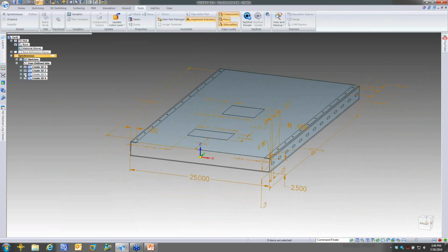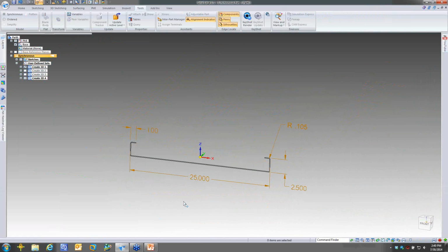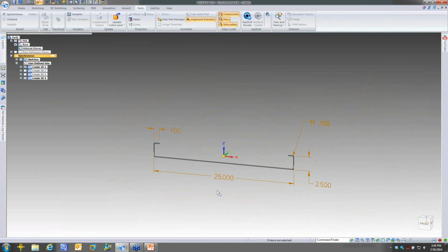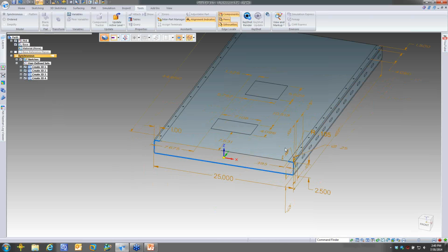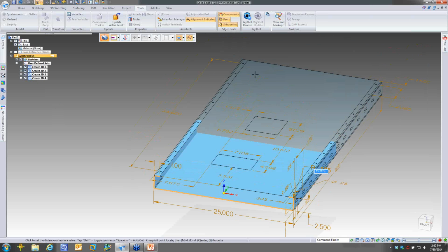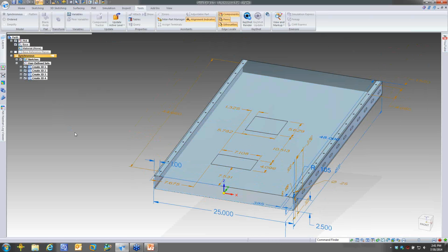But I actually want to have a nice model of this that I can utilize inside of my 3D design. So what I'm going to do is hide a couple of the views, and let's just, for example, look at the cross-section here on the front view. And I'm just going to select that geometry, and then I'll turn the other views on as a reference. And utilizing Solid Edge with Synchronous Technology, I can utilize those views as a reference for the 3rd dimension.